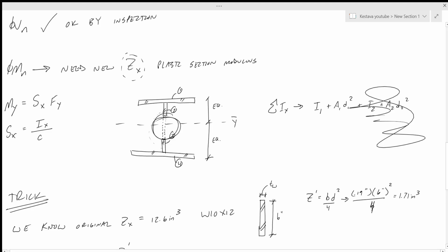So as you move further away from your neutral axis, say you clipped off a portion of the flange, or, God forbid, they took off the whole bottom flange, that's when a lot of things start going wrong. That's because you're taking away a component that is far from your neutral axis.